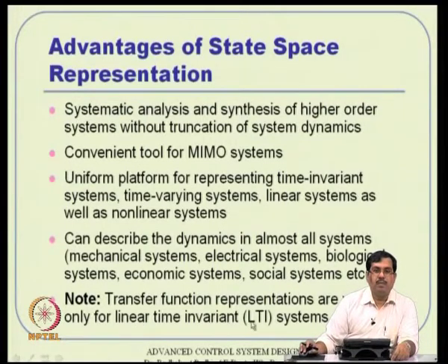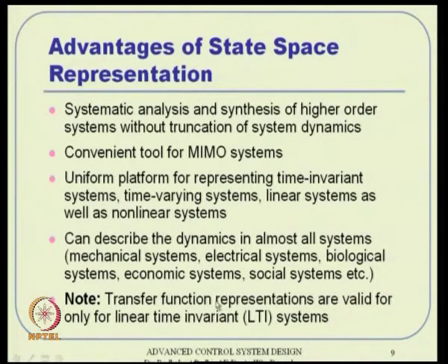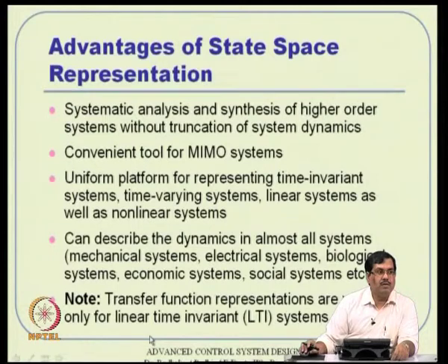I have purposefully not put SISO, single input single output, because of that reason. You can still talk about transfer function matrices. However, you should always remember that it is only valid for linear time invariant systems. The system has to be a linear system and the parameters must not be time varying. If it is a time invariant system, only then do you talk about transfer functions. Okay. Otherwise, the transfer function representations are not that attractive.